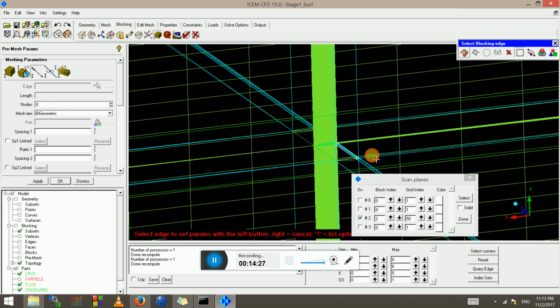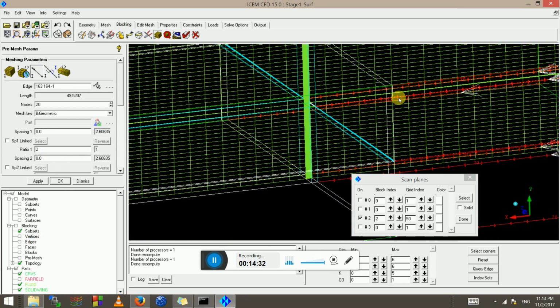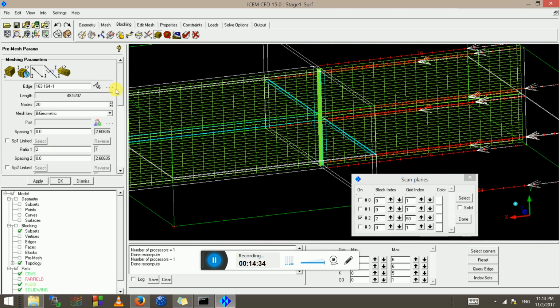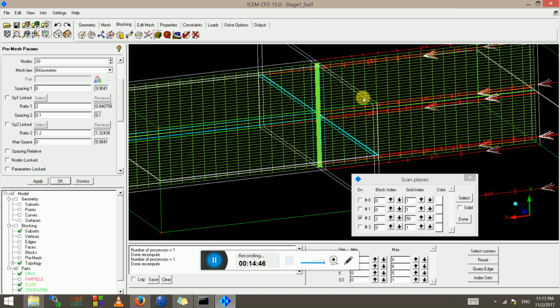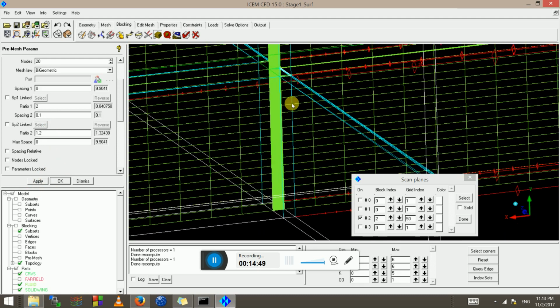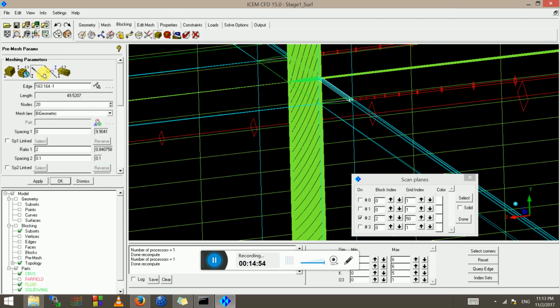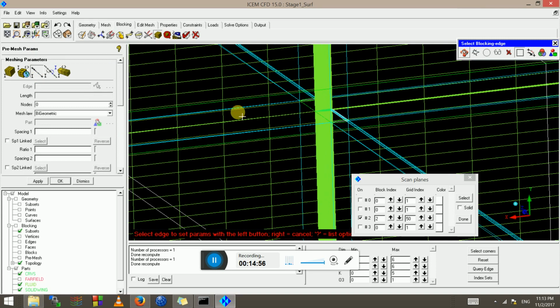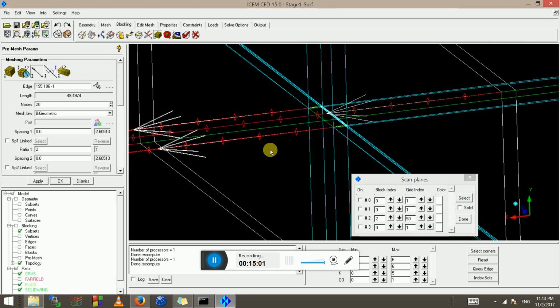let's just play with the spacings a bit more before we do that. So these edges are coming towards the wing, and I can decrease their spacing by 1.2 and spacing 2 to be something like 1 or maybe 0.1. Apply. Yeah, that's good enough for now, and click this direction. Let me turn this scan plan off just to make things a bit more visible.